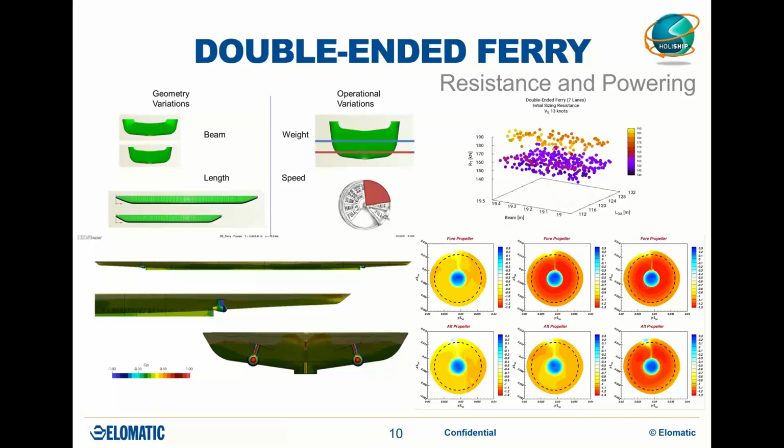At the bottom, you can see the result from the propulsion analysis, where the optimal position and load balance were studied for boats having a propeller diameter of 1.7 meters. The propulsion analysis revealed that the optimal load is obtained when we mainly use only aft pods.